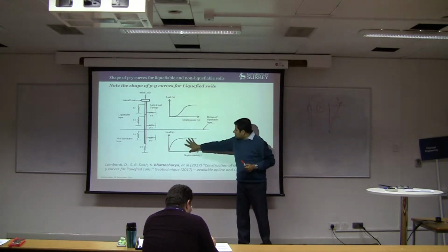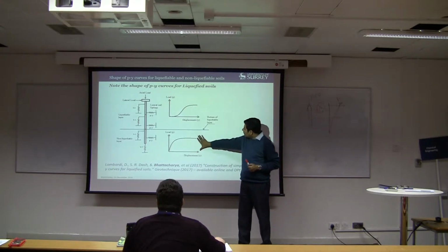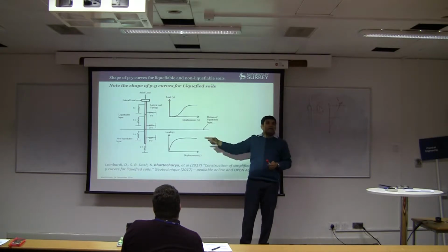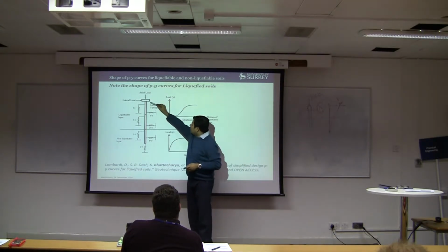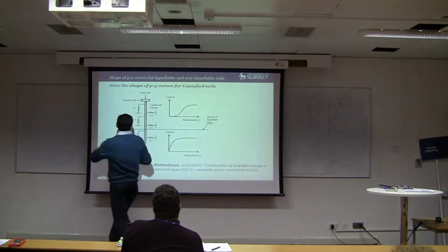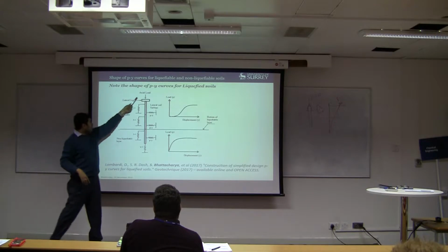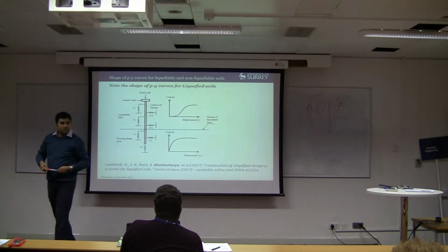Give p-y springs for non-liquefied soil and liquefied springs for liquefied soil, and run the analysis. Put the vertical load there and the lateral load there. The lateral load will come from response spectrum method, right? And vertical load will come from the vertical load of building.